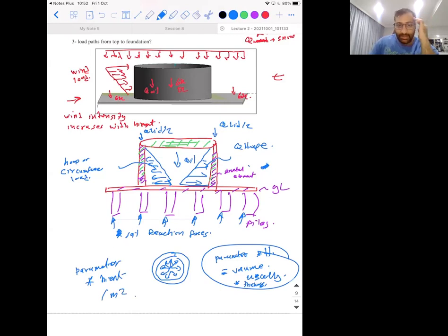Let's recap, yeah? Water tank, oil tank, whatever. So we have a lid, and we have walls supporting, we have the slab supporting, and we have the piles supporting. And all of that is there to carry the oil inside, the lid, and the structure itself. Cool. This is a free body diagram. Some people will maybe think there are more things, like we said, wind, right?